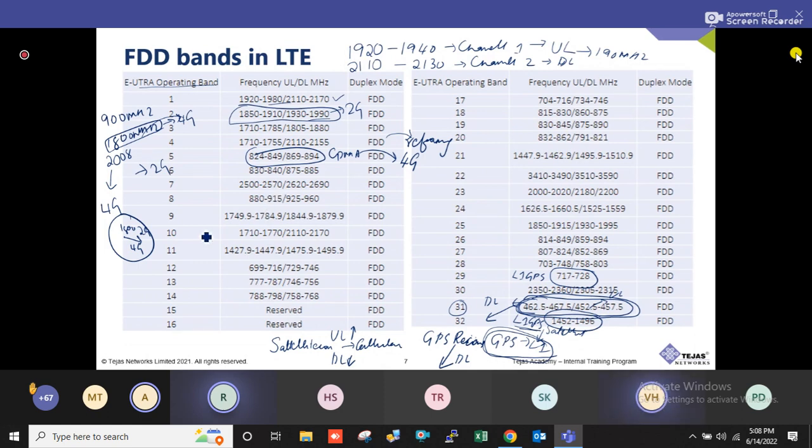Sometimes you might see this, just extra information which we understand with 4G. In the 1800 band, if you are using it for 4G, we can simultaneously use it for 5G also. This is being done by most of the operators in other markets. This concept is typically called DSS, dynamic spectrum sharing. So we share the spectrum of the 1800 band for 4G and 5G. In India, we don't see this implementation, but standards have been developed for this, wherein we can have a 4G infrastructure implemented for 5G simultaneously.